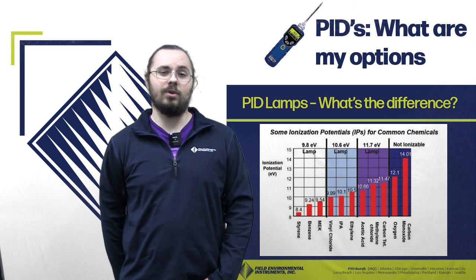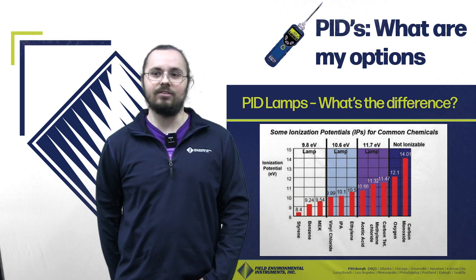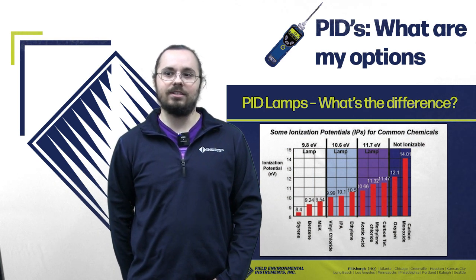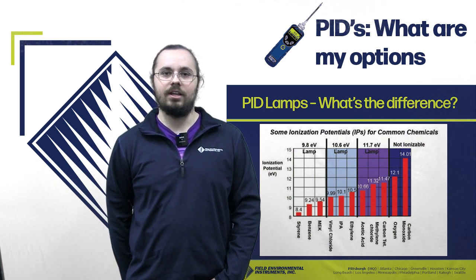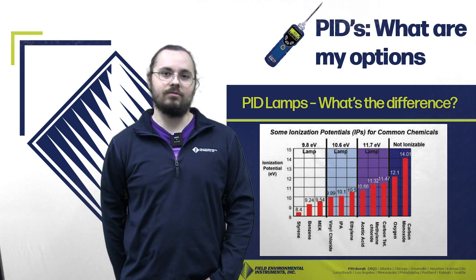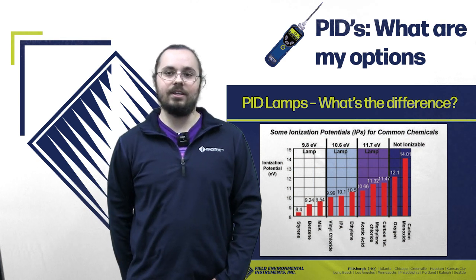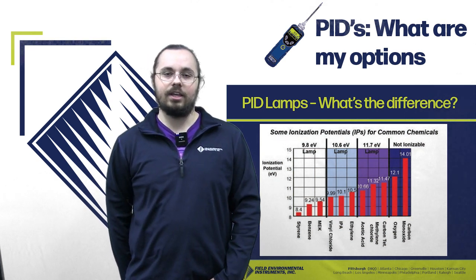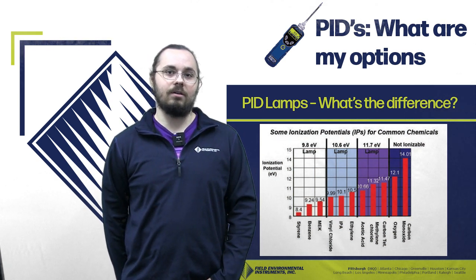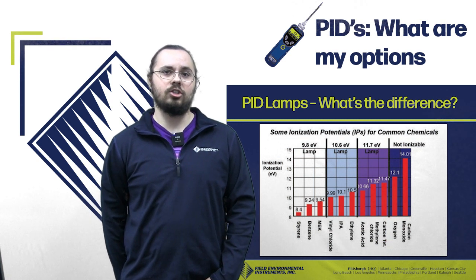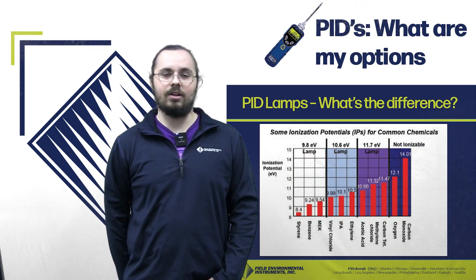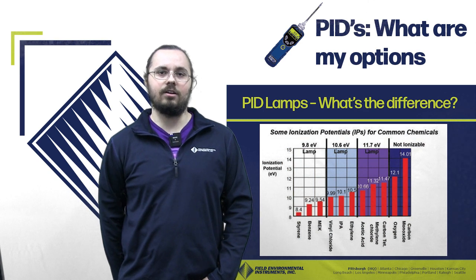Typically you'll see 10.6 eV as the standard lamp. This is mainly because they have a high resolution and typically have pretty good lifespans from around 2 to 3+ years. 11.7 eV lamps, on the other hand, can detect a higher range of compounds. However, they have a much shorter lifespan, in around the 2 to 6 month range, and are much more expensive to manufacture.